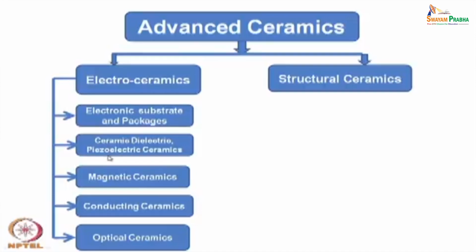Then you have dielectric properties. Ceramic dielectrics: the insulating materials also have a good capacitive or dielectric constant, and therefore some of these oxides can be used as miniature capacitors, particularly in the electronics industry. Many of these dielectrics once again have a very special property called piezoelectric property.